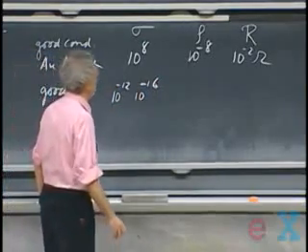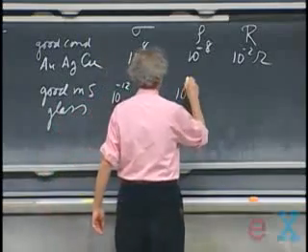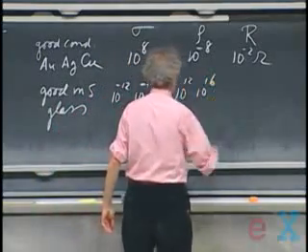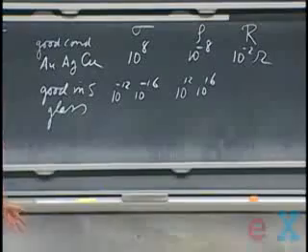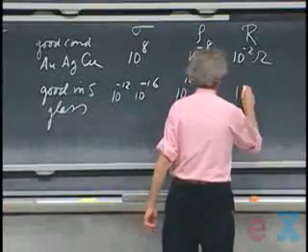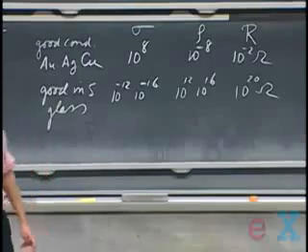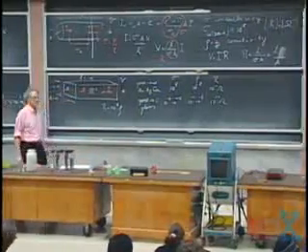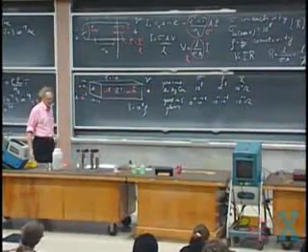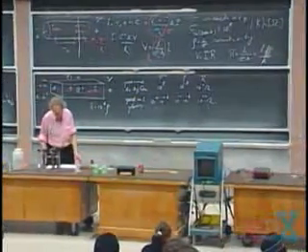So rho now, the resistivity, is something like 10 to the 12 to 10 to the plus 16, and if I take 10 to the 14, I have to grab a number, then you'll find that R now is 10 to the 20 ohms. A 1 with 20 zeros, that's an enormous resistance. So you see the difference, 22 orders of magnitude difference between a good conductor and a good insulator.